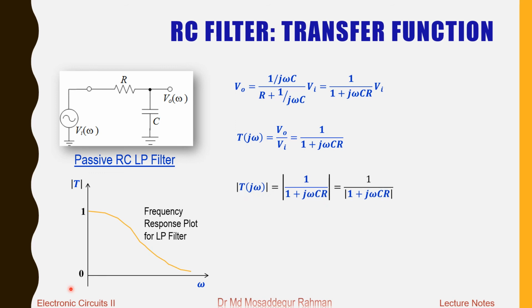So for that, again, we need to take modulus to find the absolute magnitude of this transfer function, and that we can express like this: when you take modulus, a square plus b square, and then evaluate this at different frequencies to find the magnitude. We evaluate at two extreme frequencies. One is at 0 frequency and the other at extreme high or infinite frequency.